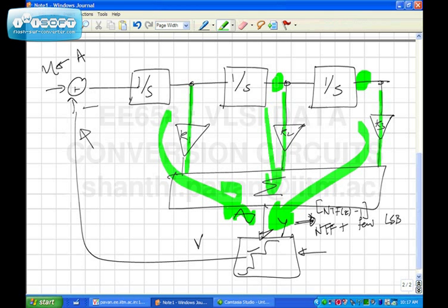So the jagged edges in this output will be higher. This of course has the smallest signal frequency component, and the quantization noise is integrated just once. So you will find that the jagged edges, or the high frequency component, of this integrated output is the largest. Is that clear? All right.